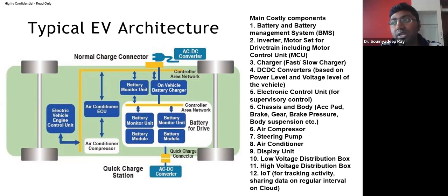Another thing it ensures is that if the SOC difference between the battery packs or between the cells is too high, then also we have to stop. Otherwise, the battery balancing would not happen. So this kind of thing would be ensured by the BMS. So this is the number one thing.